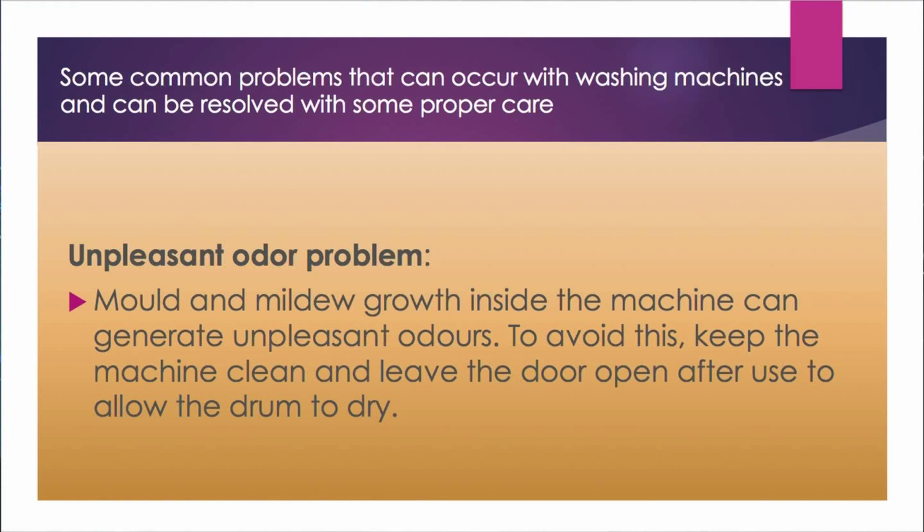Sometimes your machine may produce an unpleasant odor, and this could be a big problem. Generally, mold and mildew grow inside the machine and can generate unpleasant odors. To avoid this, keep the machine clean and leave the door open after use to allow the drum to dry properly. If you experience any of these issues with your washing machine and are confident that you can resolve them at home, only then should you try at home. Otherwise, you should always contact an authorized service center to repair the machine.